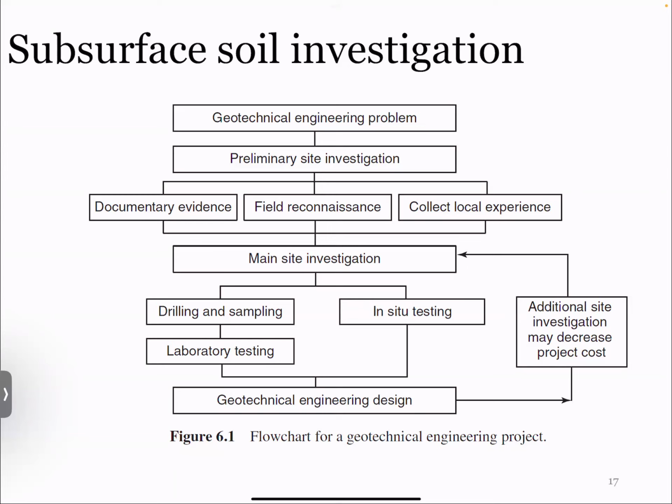So let's say you're doing a multi-phase residential area. You would do a blanket geotech report for it, and then be like, well, okay, this northwest corner has some potentially problematic soils, but the other quadrants are okay. So you can start constructing on here, but we suggest doing a little bit more in-depth design and analysis over on that northwest corner, you know?